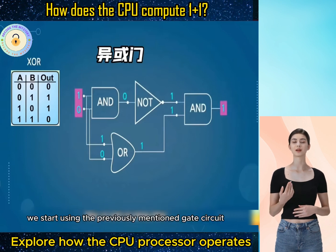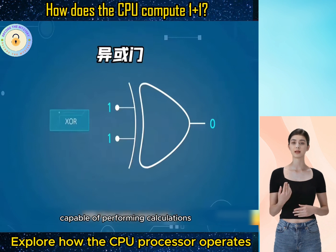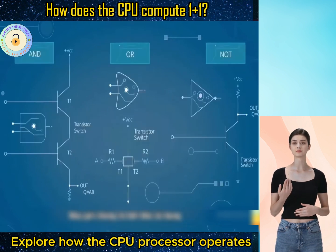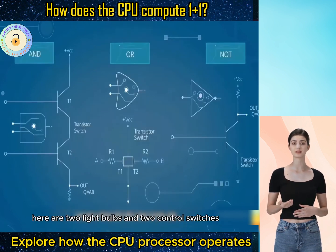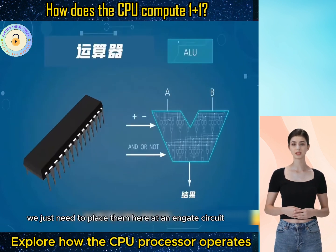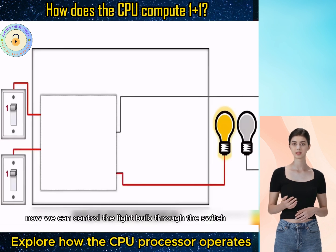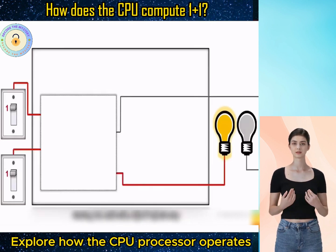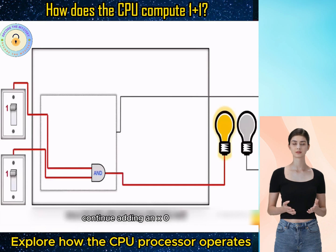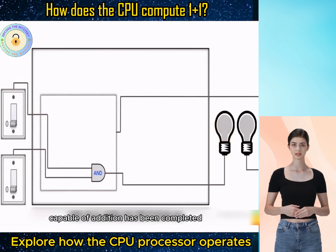Now we start using the previously mentioned gate circuits, combining them to create a set of gates capable of performing calculations. Here are two light bulbs and two control switches. We just need to place them here, add an AND gate circuit, then connect to the left light bulb. Now we can control the light bulb through the switch. Next, we place them here, and continue adding an XOR gate circuit.